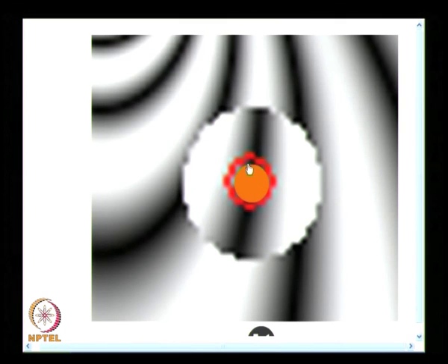For illustration, I have shown a big circle, actually it is the center of the circle. So, whatever the interpretation, data interpretation is applicable only to the point of interest when I apply compensation technique. Even though I see semblance of fringe elsewhere, they do not hold interpretational value to the physics of the problem.